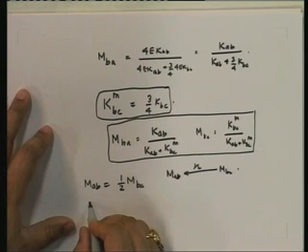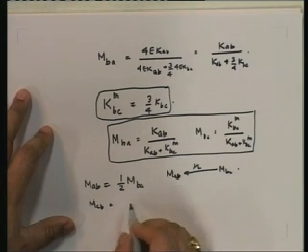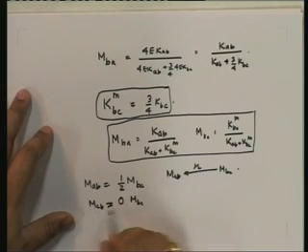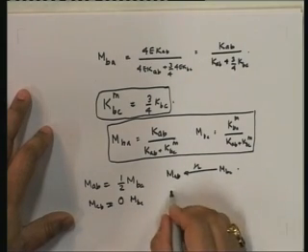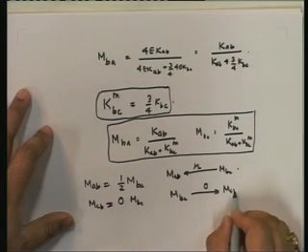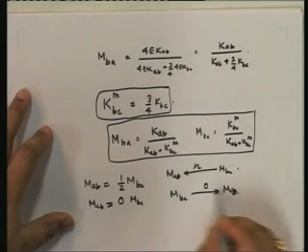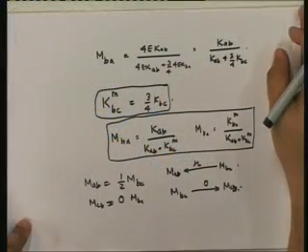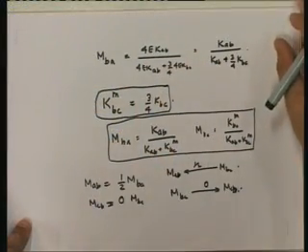Okay. However, what is MCB in terms of MBC? 0, because MCB is 0. So when you have a modified member, the carryover to the other end is 0. There is no carryover because moment cannot be carried over. So with these modifications, let's see how I can solve this particular problem that we have.